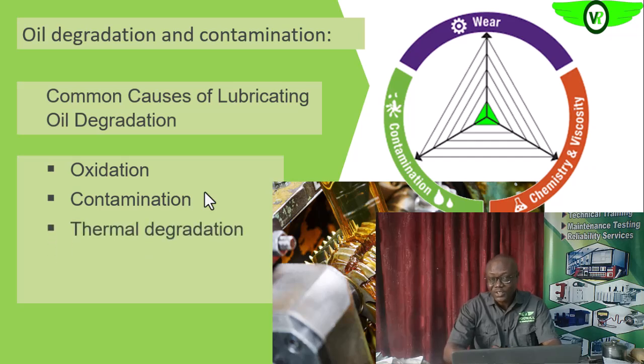So thermal degradation also, that is exposing the lubricating oil to excessively high temperature. We know that once that happens, it can cause the disintegration of the oil molecule, and then it can even increase oxidation, giving the right condition for oxidation to take place in the oil and on the equipment itself. So we want to be sure that the equipment is operated at the right temperature, does not